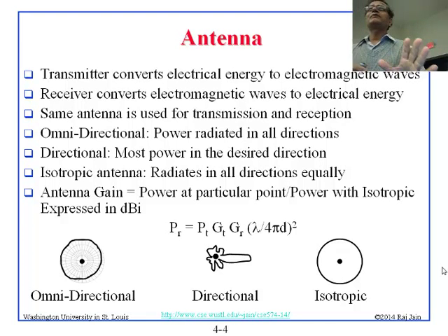Exactly the same formulas apply for the wireless. The signal is going in a sphere, and you have an antenna. Depending upon the distance, you are covering a very small part of that sphere, and so you are getting a very small part of that signal. So to increase the signal power, you really either need to use a big antenna, or you need to come closer to the source, or increase the power from the source. Anyway, this one is actually called isotropic. Isotropic means the signal strength is the same in all directions.